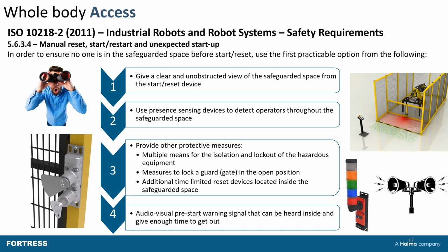So something which you take in with you, either you've put a padlock on the gate or you've taken a safety key as you go in using that trapped key technology. And that gives that control to the person going in while they have that with them, either while their padlock is on the gate or while that key is in their hand. They know it's not possible to relock that gate, giving that personal control to the person going inside.